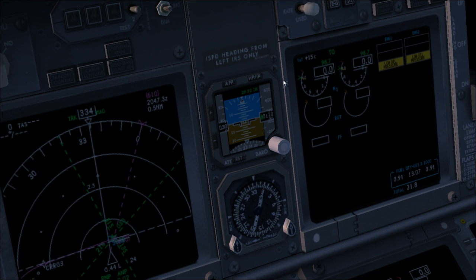The ISFD is a digital instrument. You can control its luminosity by two switches here. It presents the speed, the altitude, the barometric selection. You can select hectopascal or inches, and the reset button to reset. You can turn this knob to select other pressure, or you can press it to standard pressure. If you press approach, you can enter in approach mode, and the approach deviation scale will be set on. You have back course selection or approach mode. You can select the one you need.